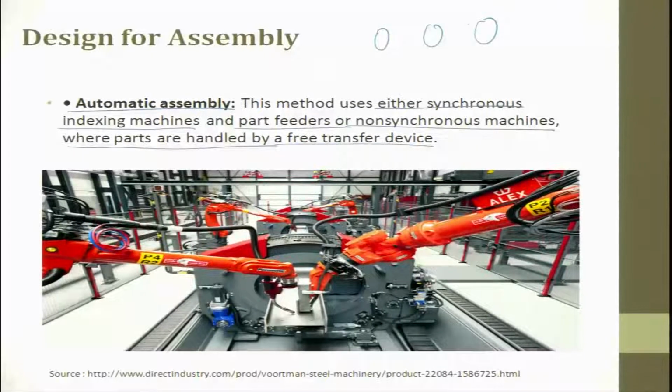If the cycle time for each station, station 1, station 2, station 3, is all balanced, 3 minutes, 3 minutes and 3 minutes, then when I move from one station to the other, there is a synchronous motion, or a synchronous indexing machine. Suppose you have 5 stations around and then you have an indexing table. Every time it indexes, the new job or the part to be machined comes in contact with the workpiece.